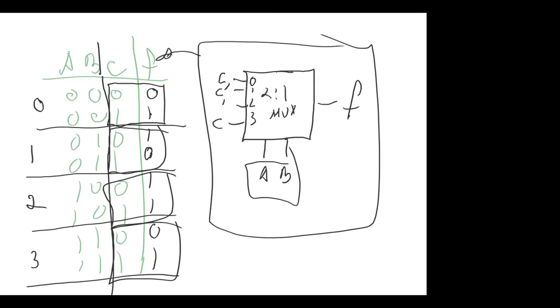What do you think of that one? In other words, you do not need a Kmap to implement a truth table if you have the right multiplexer and the know-how to use it. What do you think of that? Is that good? Good explanation? Who got confused?